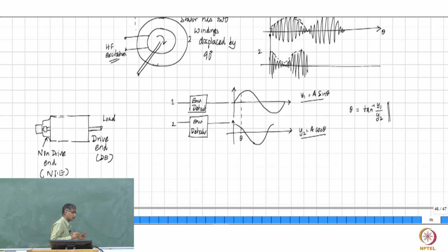So first thing is, the encoder itself may be expensive depending on how you want the encoder to be. If you want a low cost encoder which is not so immune to all the disturbances, you can get very low cost encoders and you can put them onto the electric motor, it will work. Right? Only thing is, ambient conditions etc. you need to take care, it may not be very accurate. If those inaccuracies and difficulties are acceptable for you, there are low cost encoders that are available. You can get something for very low cost, but